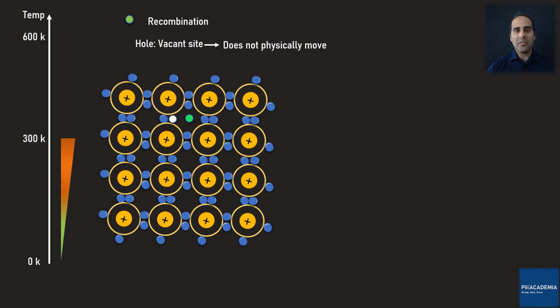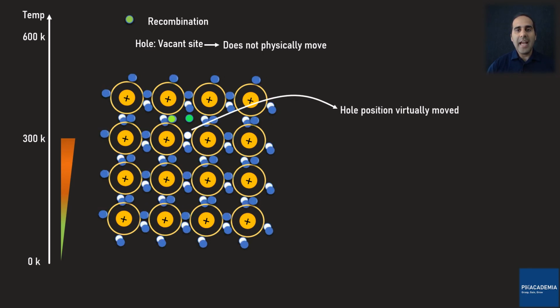Since the temperature has risen, the valence electrons are wobbling. If a covalent bond near the first hole generated is broken, a free electron comes close to the first generated hole and it is seized. Now you can see that the hole position is kind of moved. This process continuously happens in the material at temperatures larger than 0 degrees Kelvin. This animation shows the rest of the story and the way the hole is moving in the material.